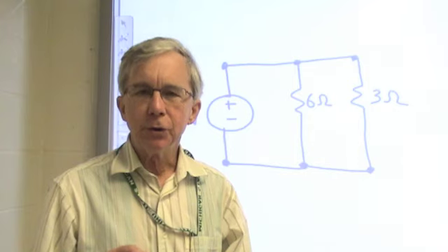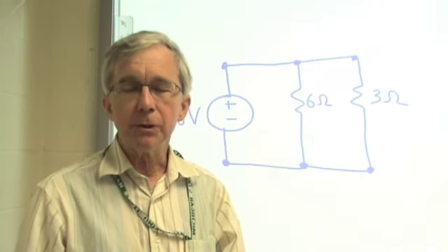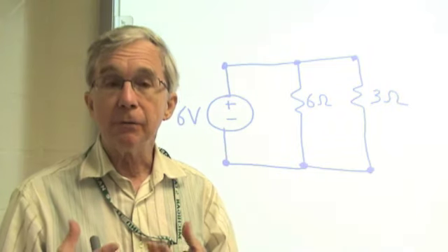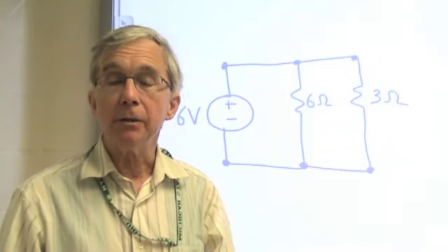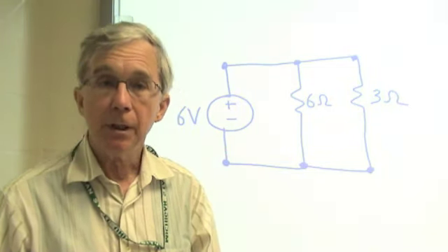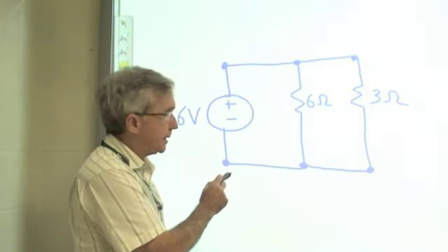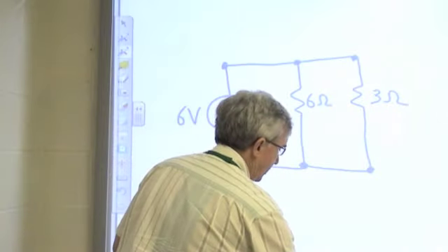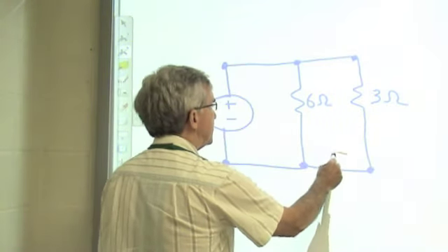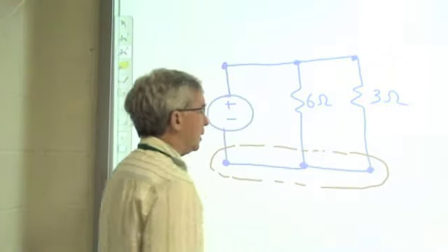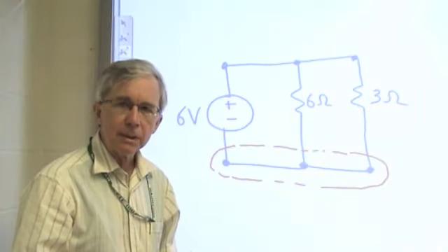We've been showing the node as a single point, but on a circuit schematic, more generally, the node consists of all the zero resistance wire from the node to each element. For example, on this circuit, we would not say that there are 6 nodes. Instead, we could think that all of these points are one single connection point.